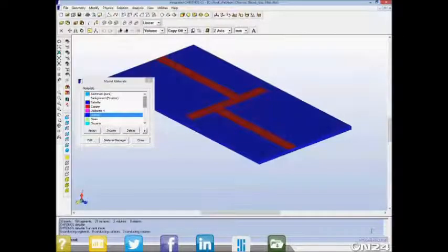The last pair of examples that I'll be showing use our most recently developed program, Chronos, which is a high-frequency or short time frame, time-dependent solver using finite difference time domain. The first model you're looking at here is a thin dielectric slab with a conductive coating on it. Of course, this could represent various things. This one is titled 3-band stop filter. The basic physics involved here could be indicative of patch antennas and the like.